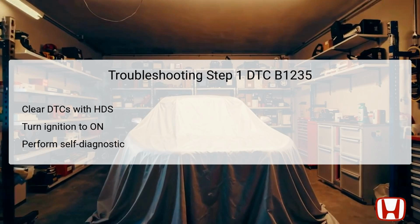After the system is primed, conduct a self-diagnostic with the HDS or the climate control unit. This step aims to see if DTC B1235 is reappearing. If it does, you will proceed to the next troubleshooting step.